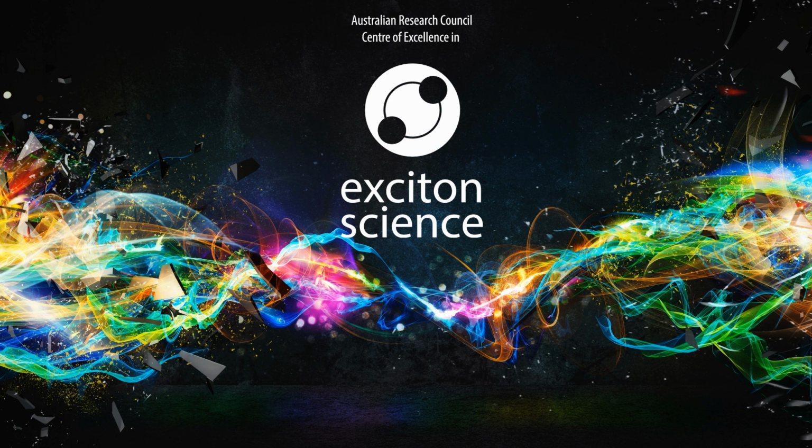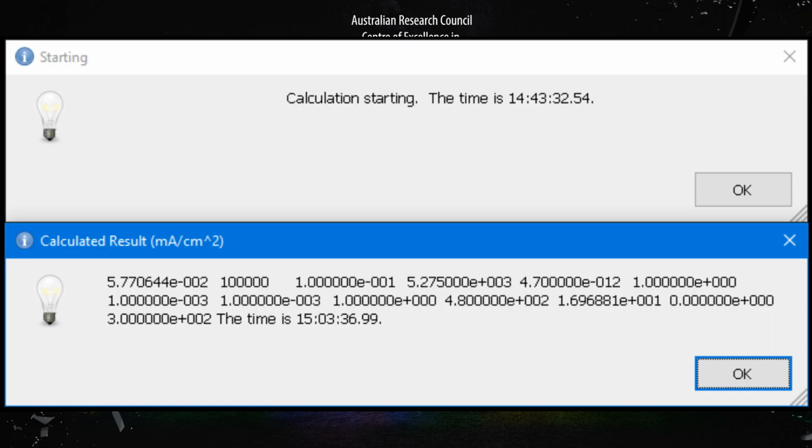Most people will do fine by assuming the ordinary standard solar spectrum, which is the file we've provided. It's much more likely that you will want to customize your emitter emission spectrum according to your choice of emitter molecule. The range of wavelengths in the emitter emission file must be within the ranges of the wavelengths in the absorption spectra. Your emitter emission file will be automatically renamed to emission.txt. Your illumination file will be automatically copied to spectrum.txt. Once you have selected all your files, your calculation will begin.